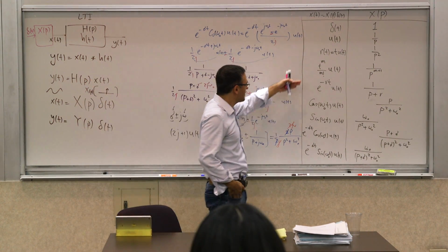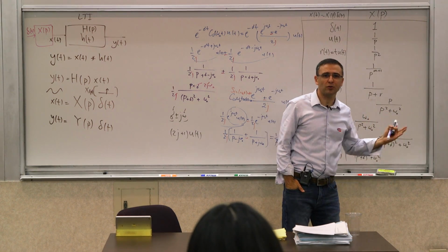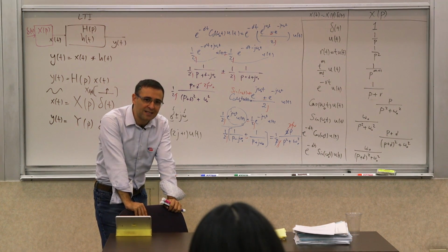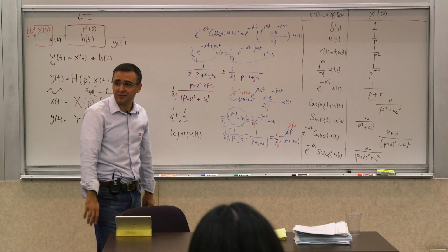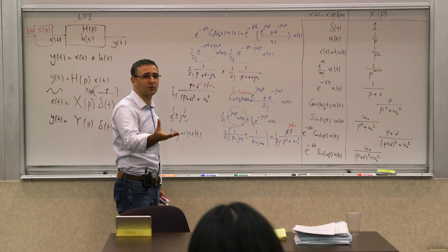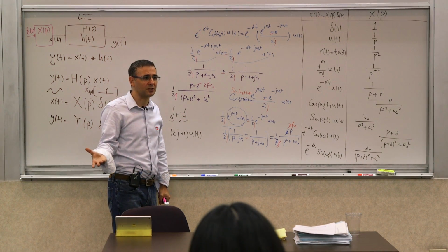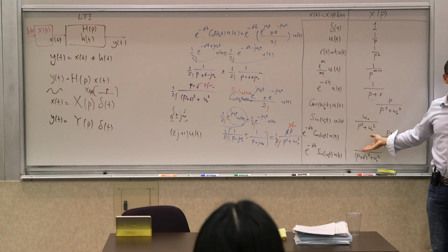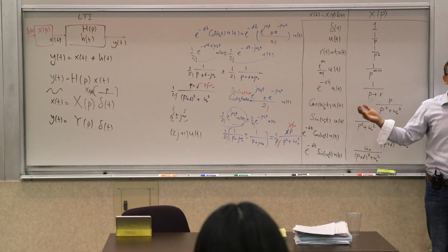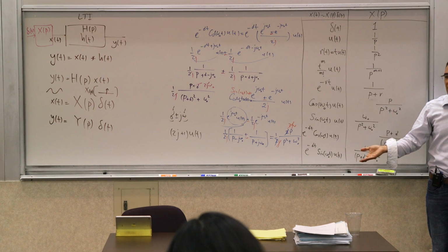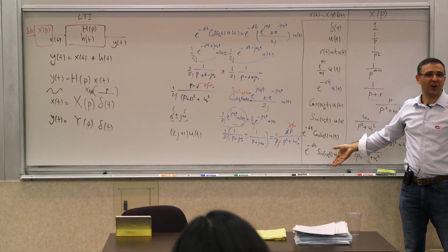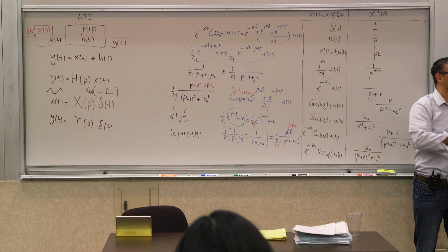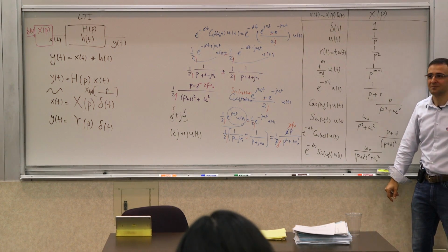Right, but these waveforms are actually capturing pretty much all those kinds of responses that we talked about, right? And you remember from the partial fraction expansion, we said, by the fundamental theorem of algebra, that you can factor any nth order polynomial in terms of first and second order polynomials with real coefficients, right? So these are first and second order polynomials. These are the only things you can get out of partial fraction expansions of rational functions. Therefore, these waveforms are essentially the only kind of waveforms you are going to get out of a system that can be described with rational functions, which would be all the lumped systems.